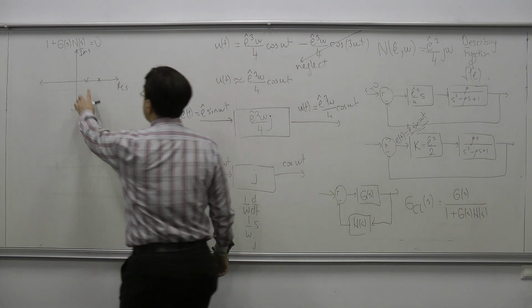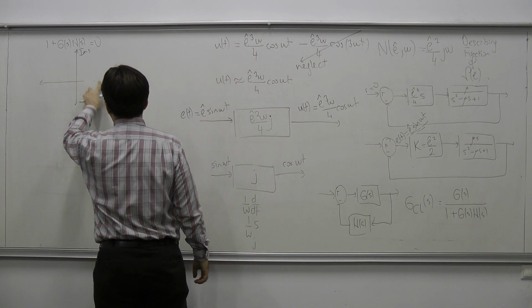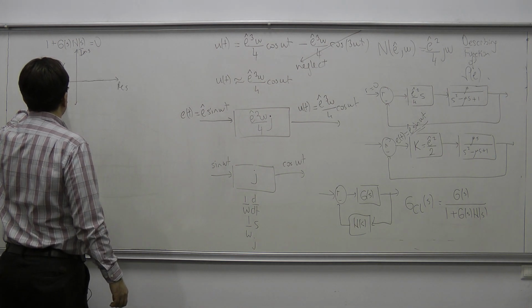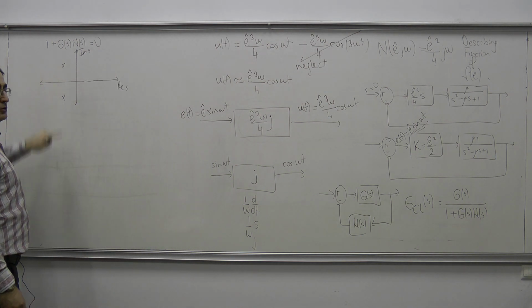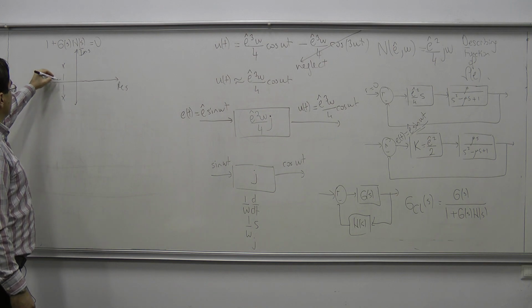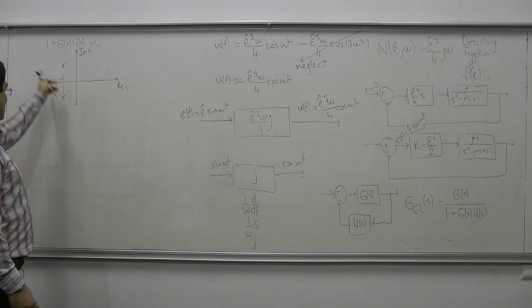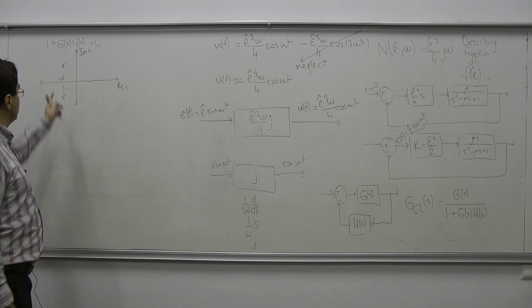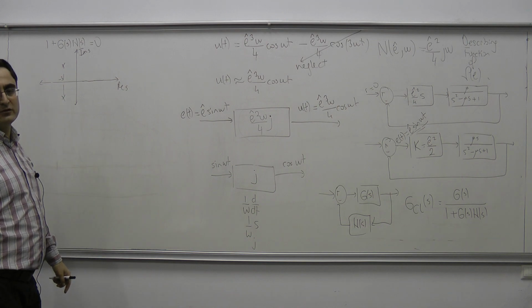Okay? So we cannot have real closed loop poles. So we want complex conjugate closed loop poles. If I have complex conjugate closed loop poles like this, so suppose that their real part is -3, I made this up. In that case, do you see sustained oscillations in the system?